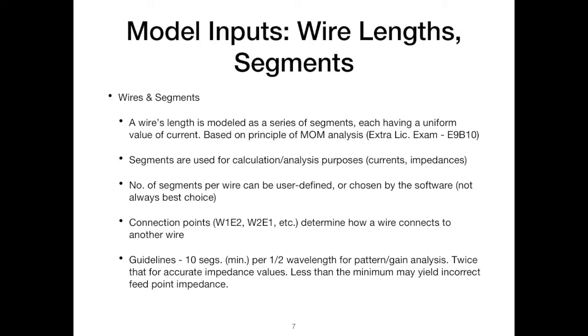Those are going to influence the outcome of the analysis and the calculations in terms of currents and impedance. The number of segments per wire, like I said, you can define yourself. You can override what the software gives you automatically.